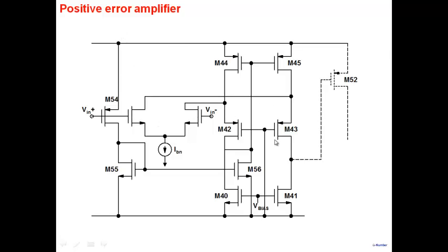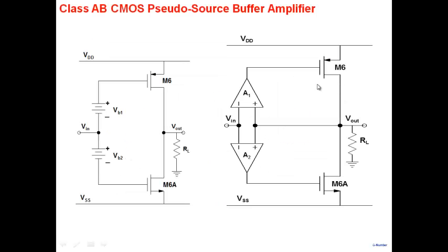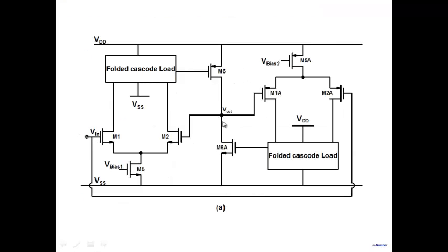All right. I'm not showing you the final circuit. This was part of an MTech thesis here. One of the students took a course like this, and all I want to tell you is to give you confidence. He took a course like this and ended up designing a very nice amplifier which works on 1 volt, plus 0.5 and minus 0.5. Same 0.5 micron technology, works with plus 0.5 volt and minus 0.5 volt, a 1 volt amplifier here. Okay, and so this was based on something of this kind here. Okay, with error amplifiers and folded cascode.